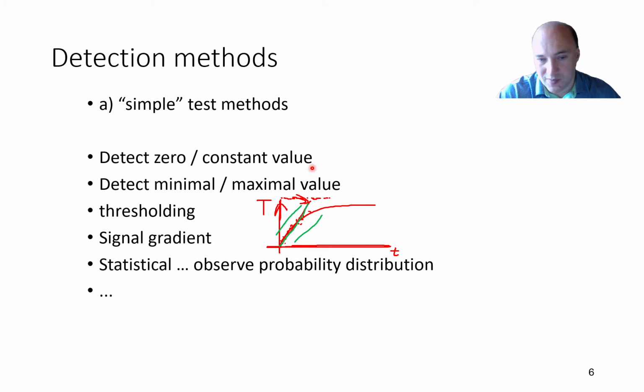So the way this is typically done is that you turn something on, such as a heater, and after some specified time you will verify if the temperature has changed. So for example, you start at some initial temperature, you say, okay, I'm starting at 20 centigrades, and after 1 or 2 minutes you will check if the temperature is significantly larger than this 20 centigrades. And if not, then you will signal an error saying either the heater is faulty or the sensor is faulty. So this is like a really simple algorithm. I'm sure you would be able to code your own code for that, so I will not focus on this.